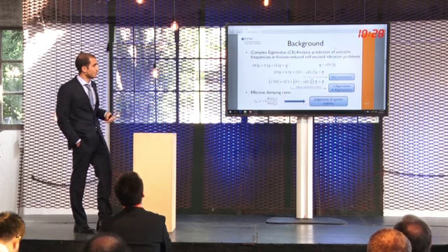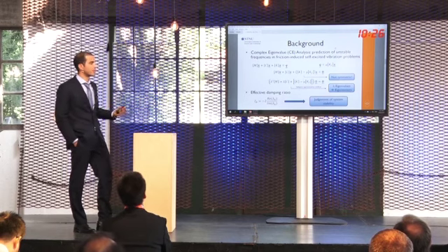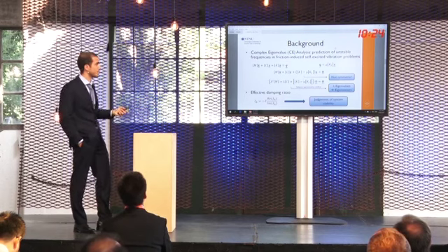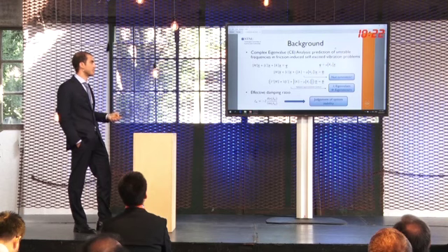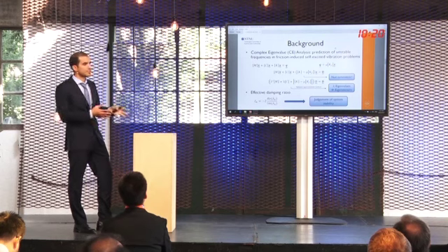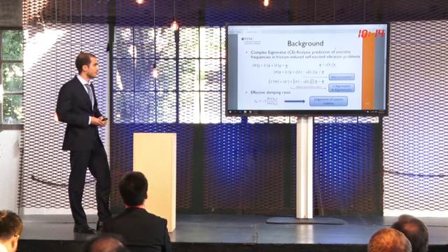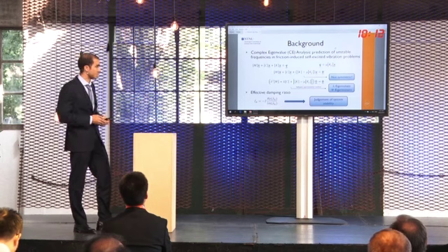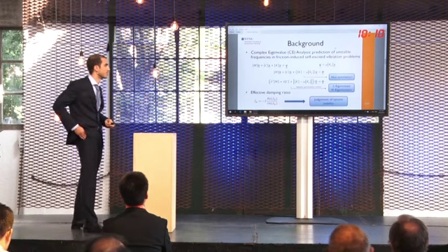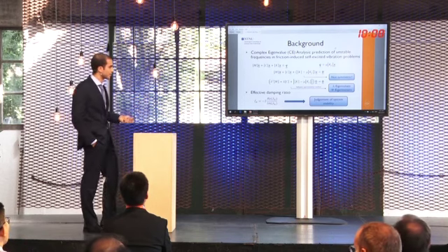If we go into frequency domain through approximation methods, in this case we have used the subspace approximation method, we can extract the eigenvalues, in this case complex eigenvalues, since we're considering the damping and the friction forces, and the eigenvectors of the system in a frequency range of interest, 0 to 1000 hertz.